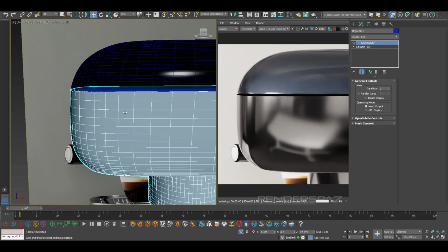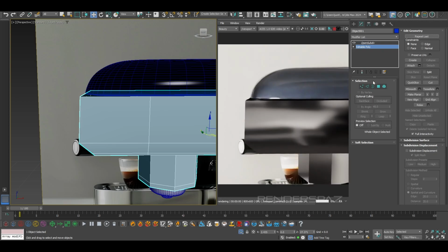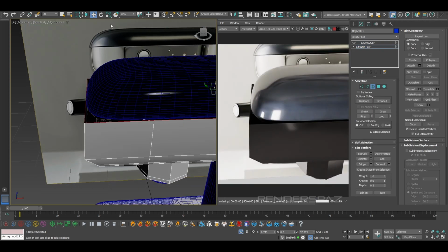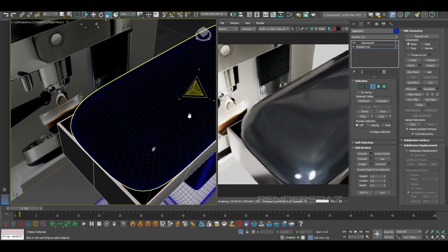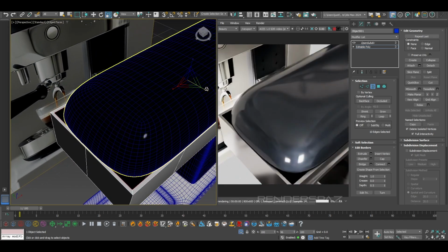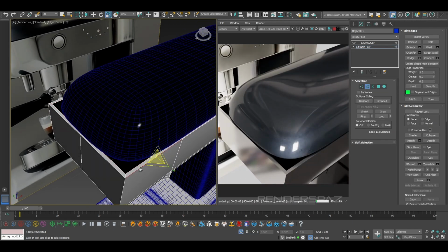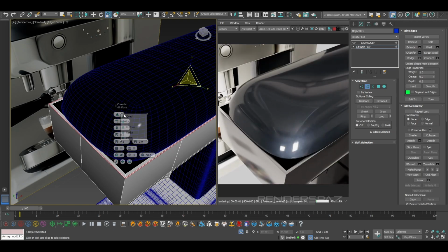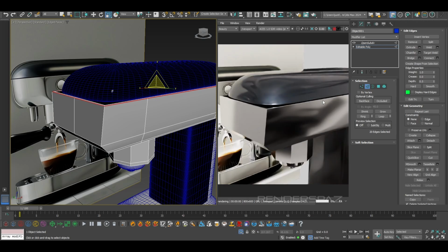So we can do the same thing with pretty much each component. So that technique right there, all I got to do is by selecting the edge, holding Shift and scaling it down, you're going to get a little bit of an edge here. So what I was worried about for the top part, you just want to make sure you scale uniform like this here in the corner as best as you can. You don't want to be too sloppy with it. You just want it to be nice and neat. And make sure you're on try mode here, and then just get a little extra edge.